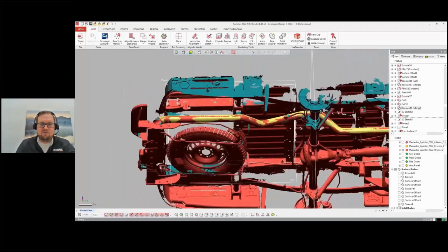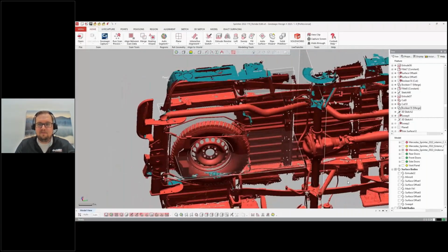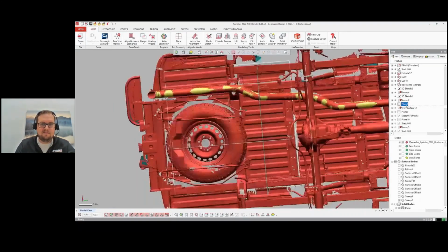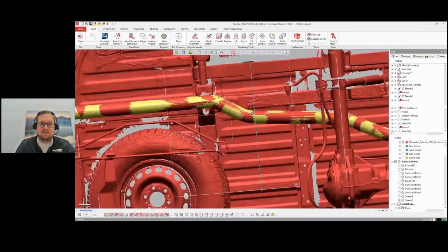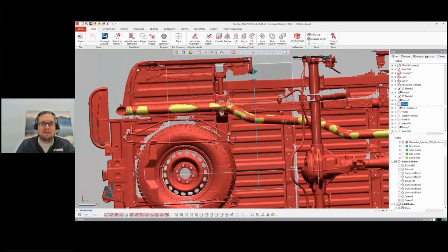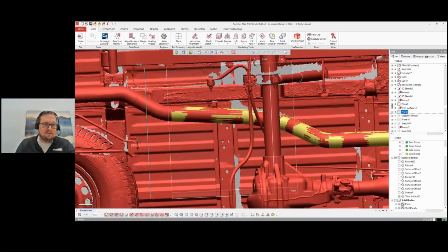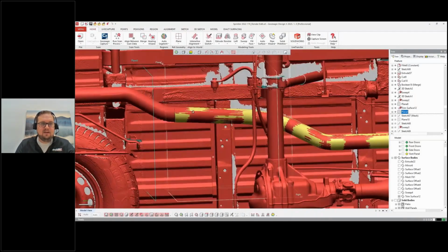Now the rear portion here is what I want to trim off. So again, this is a CAD surface feature. I can interact with it just as I would with a sketched or created solid or surface. So I'm going to chop the end of our exhaust off here, and we're going to remove this rear section. I want to put a pair of twin water tanks just at the rear of the vehicle. So go ahead and clip that off with a plane here.